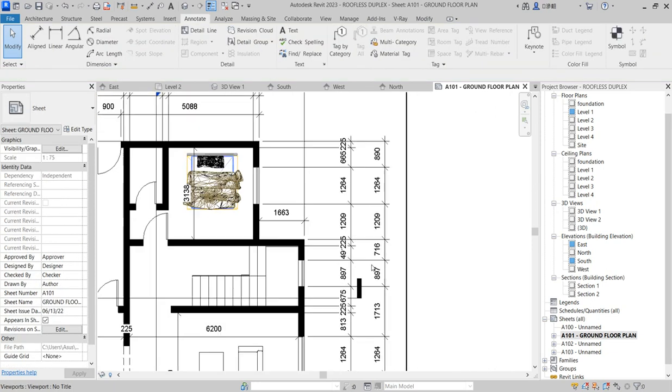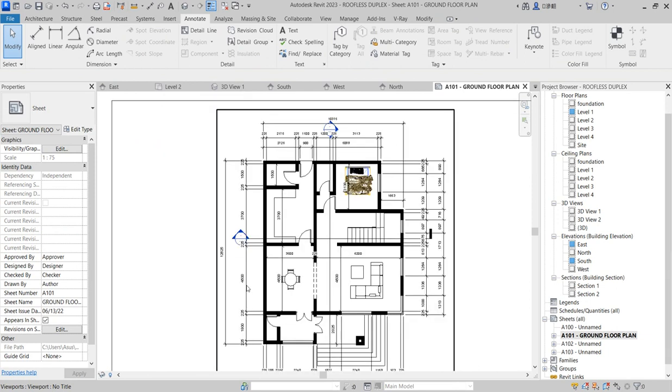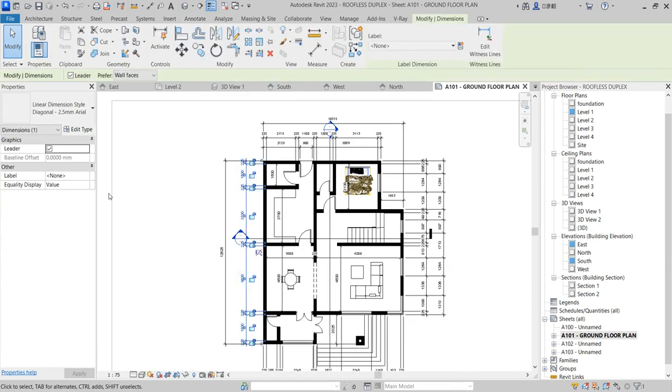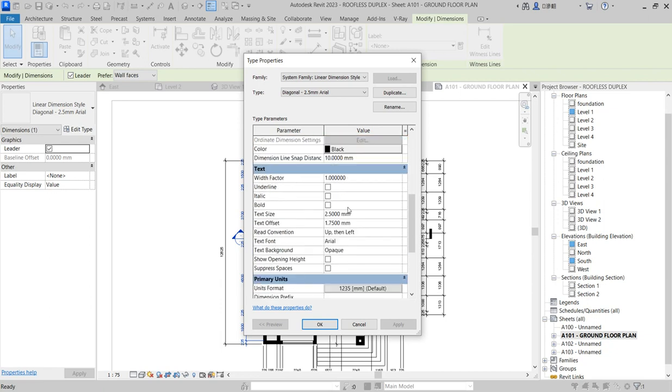You see that most of this, if it's okay by you, fine. If it's not okay for you, you double click and there you exchange, then you edit the linear. This is how you edit the annotation. So these are the figures. At this one, you change the height, you change the size. You can increase it to 3, then apply. You see it more bigger. So you change the font. You can change the font as well to our normal font.